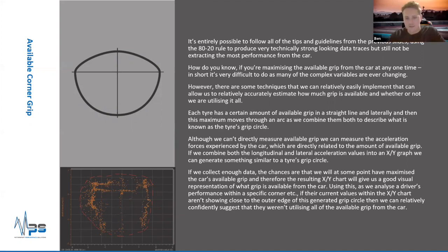So technically everything's right and they're doing it well, but they're not maximizing the limit. They're not applying the brakes as fully as they could. They could shorten the time from throttle pickup to full throttle, or they could have a few more Ks. When they release the brake, they've got the right shape, but they could have released the brake slightly earlier and therefore carried another 1 or 2 K through the corner. The hard bit is working out where those limits are.